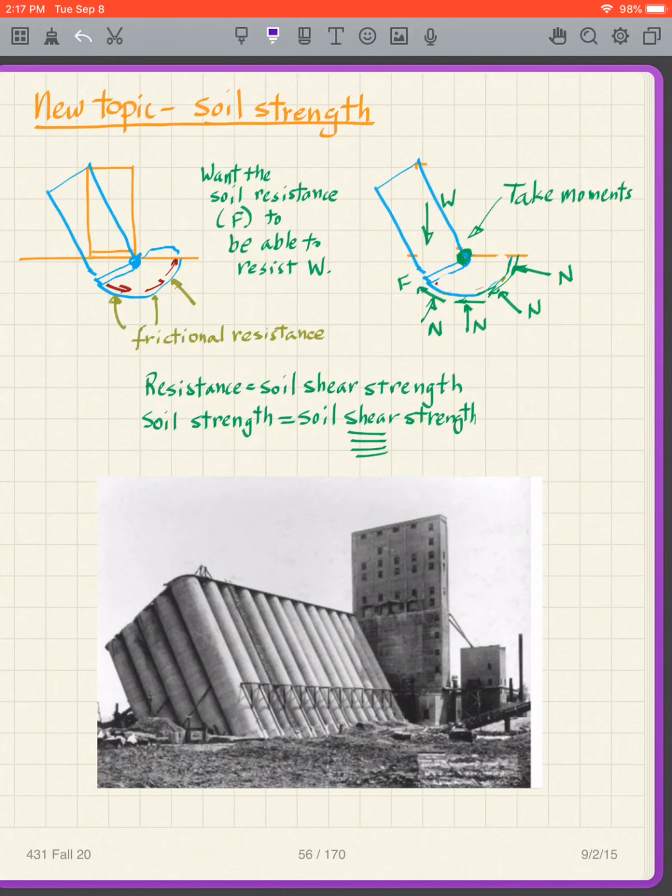If you remember, when we have soil strength, one way we are concerned about it is that I have a structure here that is standing up vertically, and what we're afraid of is that the structure is going to rotate and basically tip over. And what's happening underground that you really can't see when a building or structure does this is that we get a shear failure down here underneath the structure. And that takes place in approximately a circular shape, or a portion of a circle.